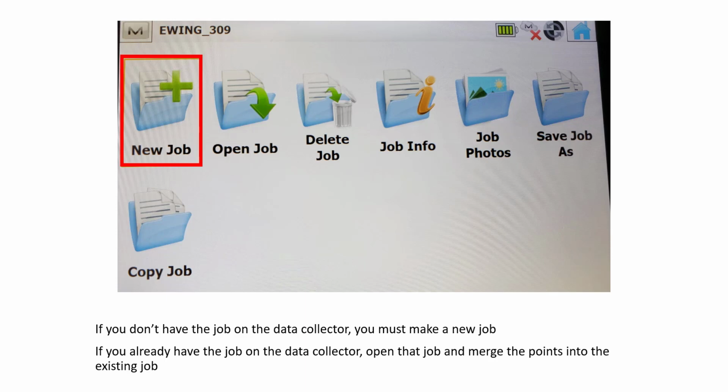But just keep in mind, because I've had it happen before, say you go out in the field and do a survey and take an additional benchmark. For example, you have 3 benchmarks, you add a benchmark. A week from now, you put on your survey points, you get ready to stake it out. What you do is you export your points and you overwrite that file. Well, now that benchmark has been deleted.